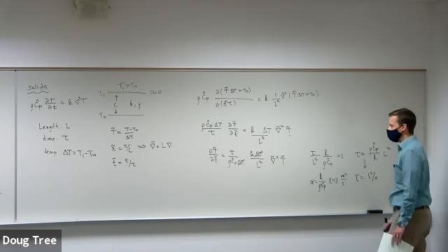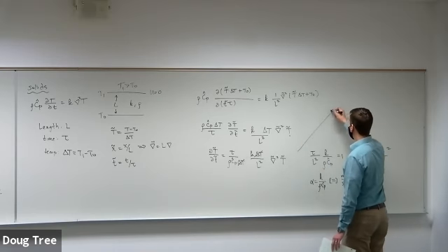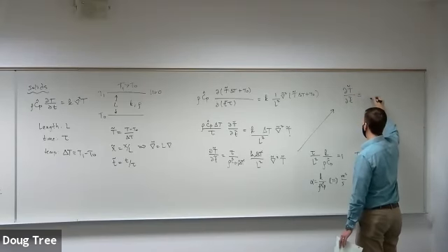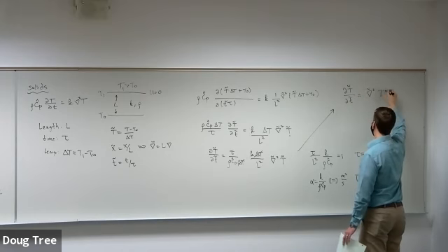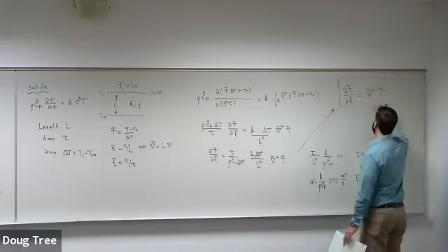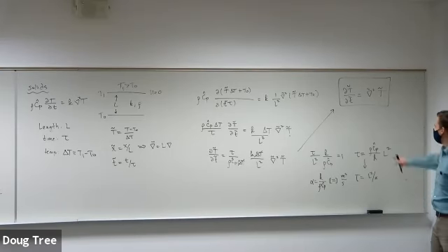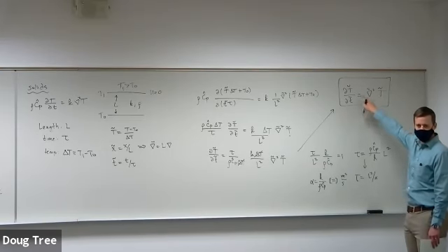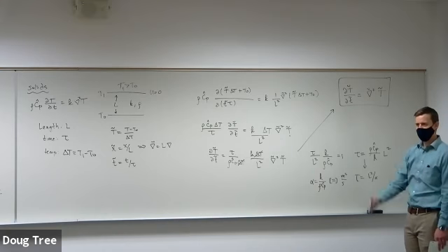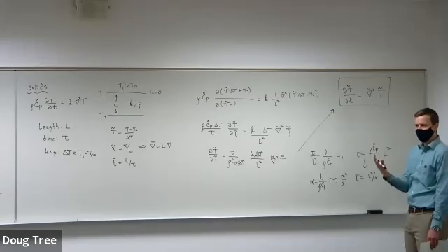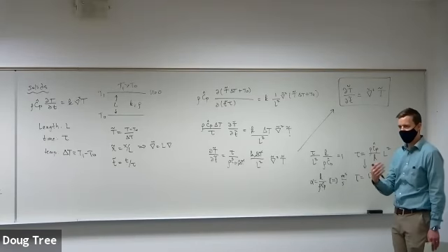So what's going on here? What I've ended up doing, sort of out of order here, is I now have d t tilde d little t tilde is equal to grad squared t tilde. Okay, I just have a diffusion equation, where the dimensionless number here is just 1. So there's no dimensionless ratio. But I have a different time scale. It's a time scale that comes out of a diffusion problem instead of the time scale that comes from convection.